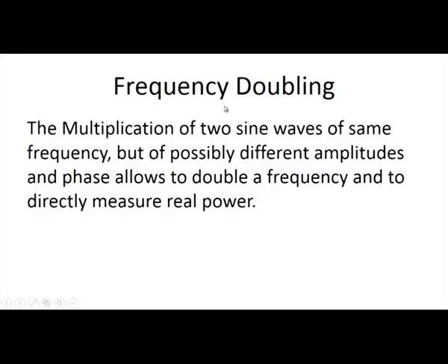This is one of the applications, frequency doubling. The multiplication of two sine waves of the same frequency but of different amplitudes and phase allows us to double a frequency and to directly measure the real power. You have to give two sine waves of the same frequency but with different amplitudes and phase.